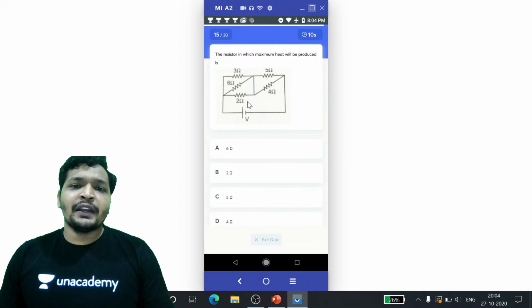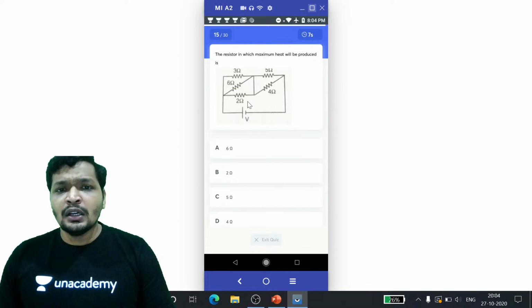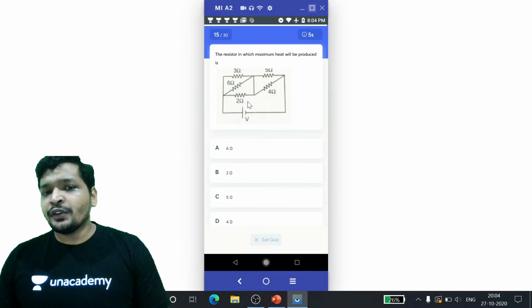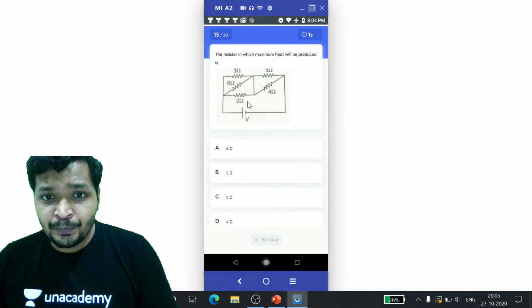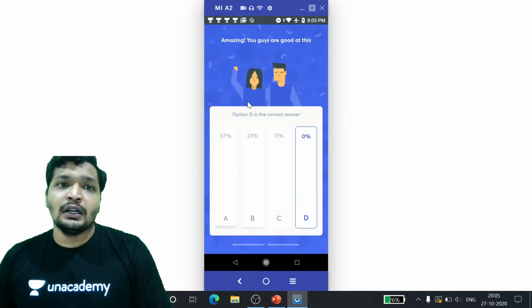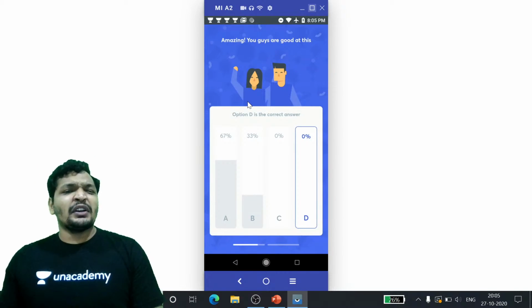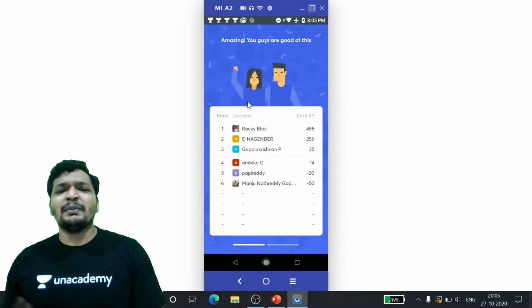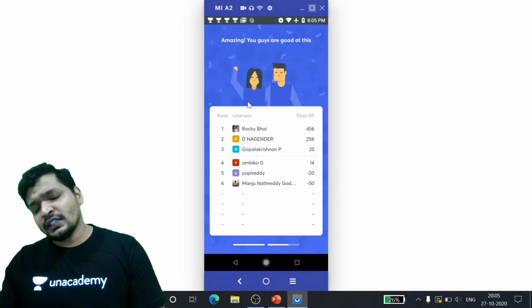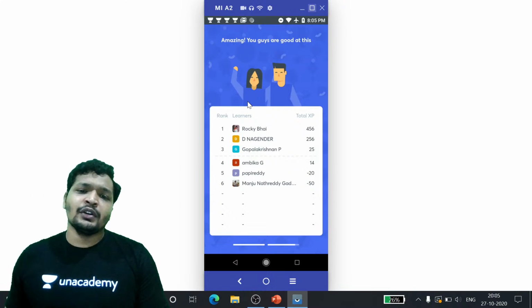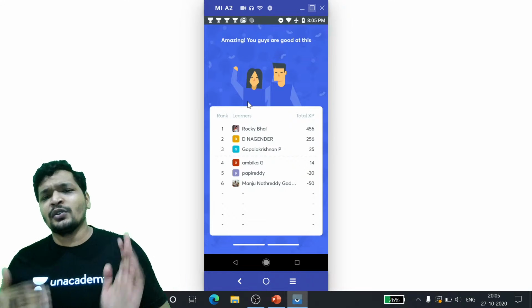So this is going to be 5 into 4. So 1 volt is going to drop across 1 ohm, that is the first one. The second one is going to be 5 into 4 divided by 9. So that is 20 by 9. So either you can go by the potential method as well, but the current method could have been a little bit easier, in that case how current is going to divide and quickly intuiting what it is. Still, I think the potential method could have also worked.